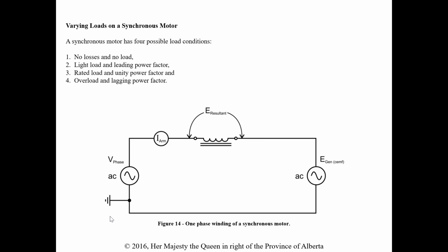So to continue on with our synchronous motors here, this would be the start of objective 4. So we talked about the construction, the advantages, the disadvantages, how that rotor locks onto the rotating field from the stator, what happens if we put too much load on it, it increases that torque angle. Again, to a point where if we put too much torque on it, we could actually rip it out of magnetic locking.